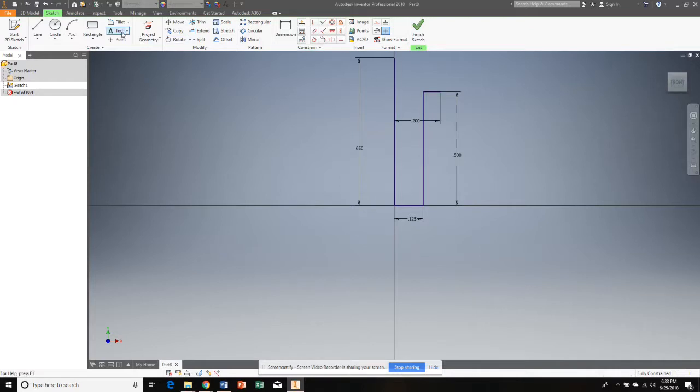Now I'm going to come over here and I'm going to do an arc. It's going to be a 3-point arc, and what I'm really going to do here is choose from here into here, and it's creating a line going straight across. I'm going to click on those 2 points, green to green, and now I need to figure out where that line goes. And what happens is when you let go of your mouse, sometimes your mouse moves.